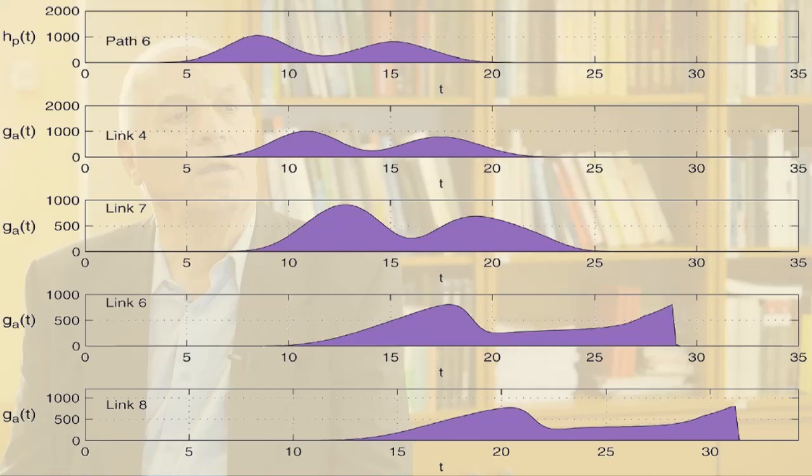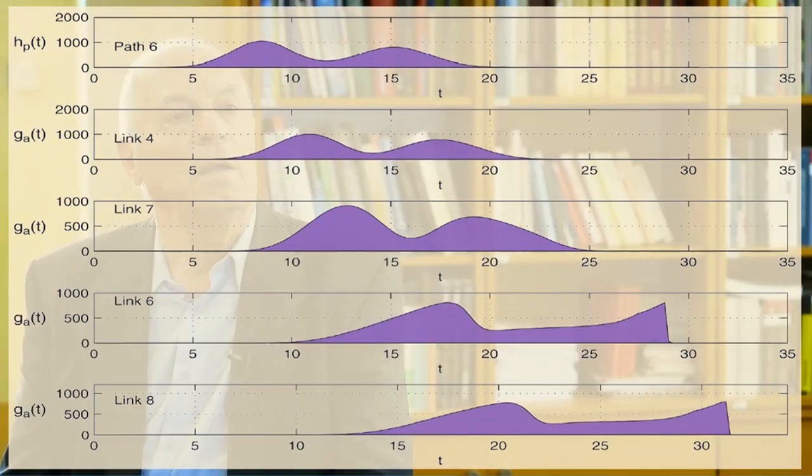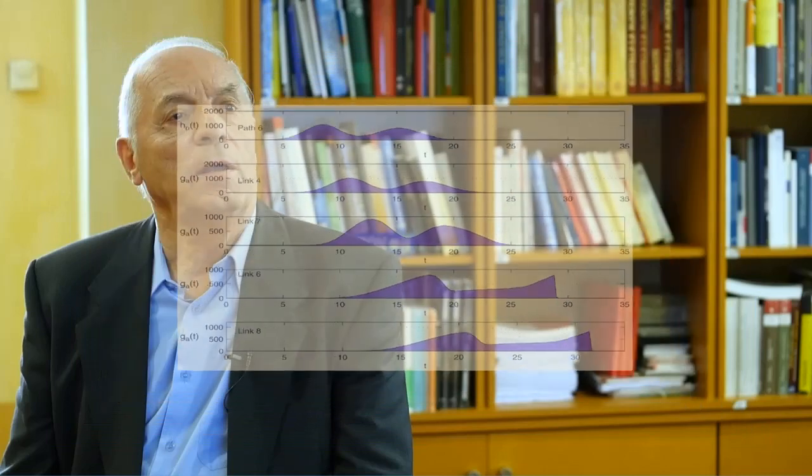At link 6, the wave suffers two different processes. One, an elongation due to congestion roughly between 22 and 26 hours, and two, a wave stretching, wavelength reduction and height increase after 26 hours on, due to the end of congestion produced by the arrival to destinations of users from other paths.